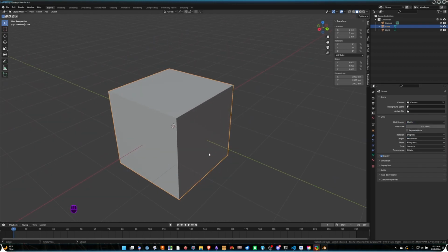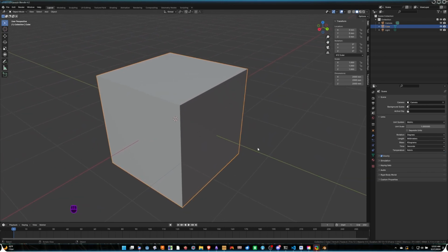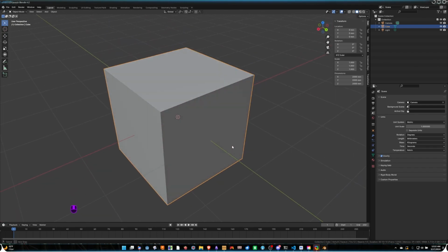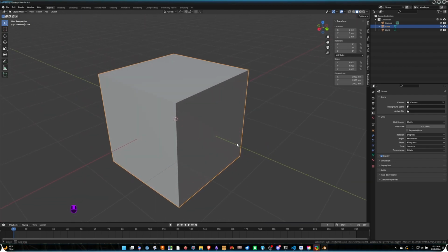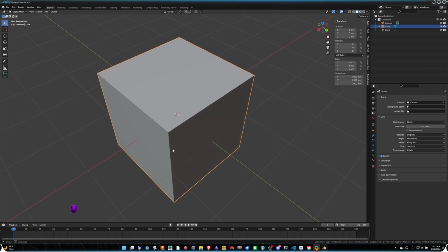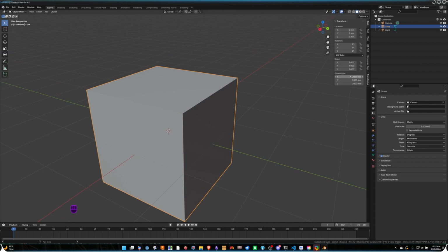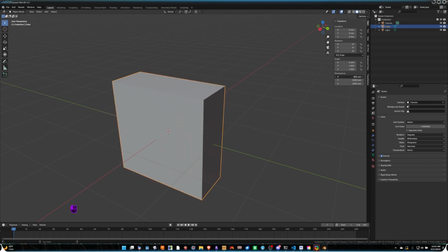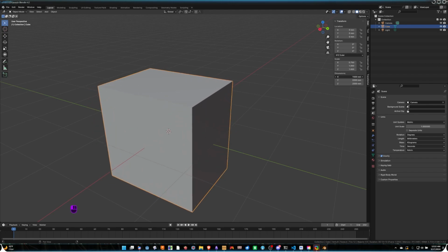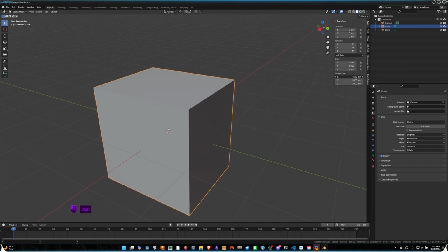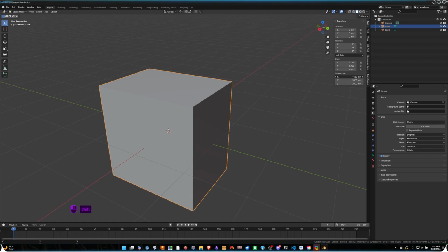Now, Blender struggles whenever it comes to certain levels of precision, but we can overcome that by manually entering settings. The same kind of thing that you'll probably have to do in Fusion 360. It struggles from the same issues. Okay, so now we can see that our cube is 2,000 millimeters. Let's try scaling it. If we scale it, we can drag this to rescale, and you'll notice that it's moving in 100 millimeter increments. If I hold Shift, it'll go in smaller increments, 10 or 20 millimeters at a time.